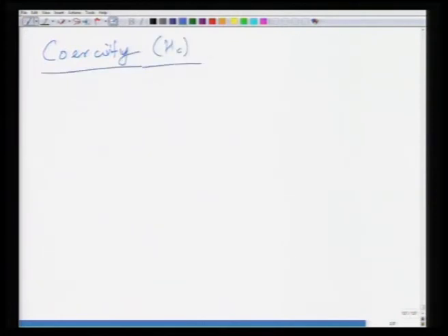which is Hc. Theoretically, if you make it really well, Hc could exceed even 1000 kiloampere per meter. However, for practical materials, it's in the low values, and this coercivity is a strong function of grain size.